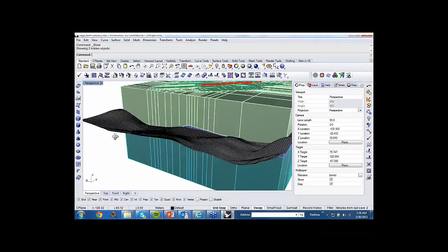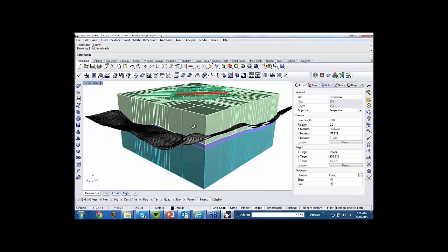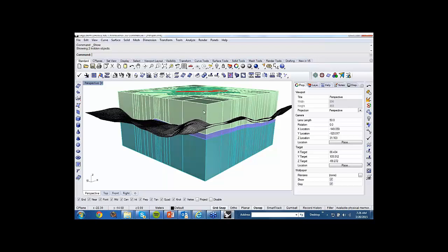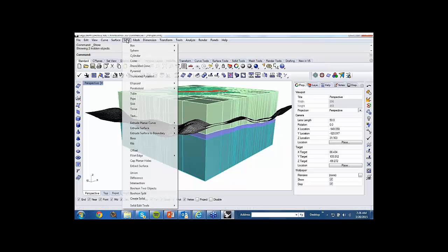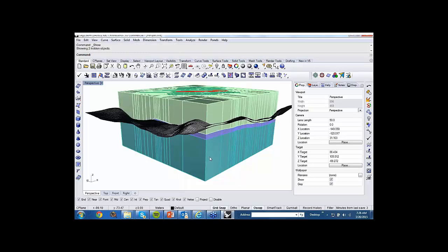These are actually two different horizons, not the ones that we used, but all the same, you can slice this collection of vertical solids with two surfaces using the solid Boolean split, which turns each column into normally three solids. You select all the solids and use Block Ranger to mesh them, and you will obtain a very good quality mesh with a very controlled distribution of zones. This is very attractive, and we've used it a number of times here at Itasca.